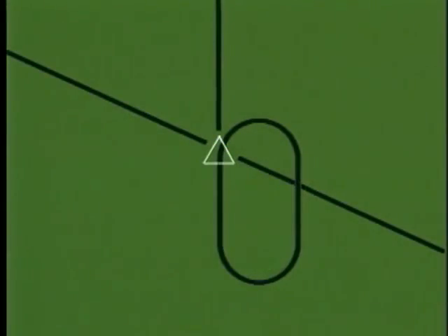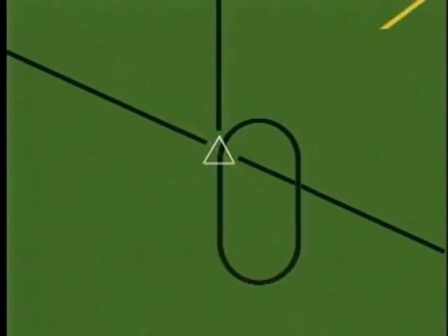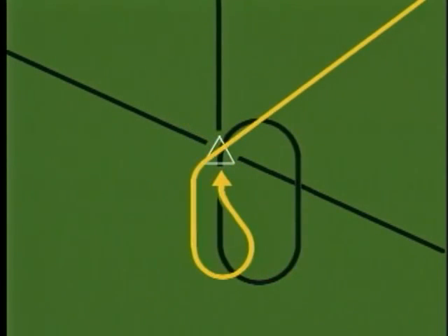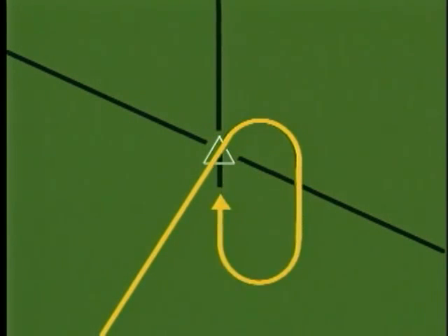To minimize the amount of maneuvering you have to do, the FAA recommends that you enter a holding pattern by one of 3 methods. Use of these procedures makes the entry simpler and reduces the possibility of penetrating unprotected airspace.